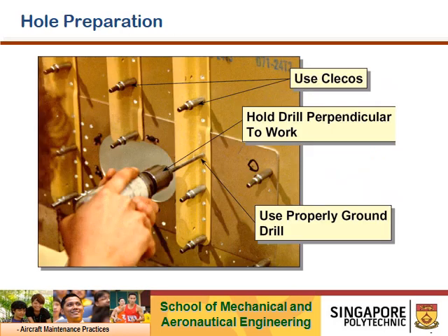Hole preparation. This is a sample picture of how we carry out hole drilling. This is a practical mode where you will experience, during your practical session, how to engage your drill bit to the drill gun and how to carry out proper drilling and posture to achieve hole roundness. This is an L channel that is attached, and a hole is to be drilled in this case onto the aircraft structure. After the hole is drilled, you can install the required fasteners.